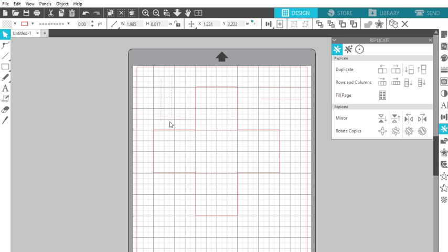I'm going to drag the first score line or fold line down onto the top of the left side, and once I've dropped it into place, then I want to select the box, and I want to use the point edit tool to create a couple of additional points so that I can drag this side back out like this.